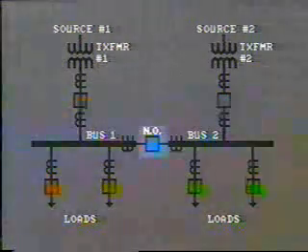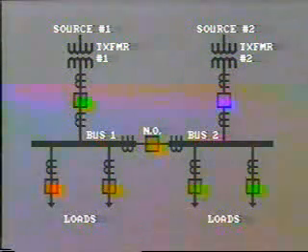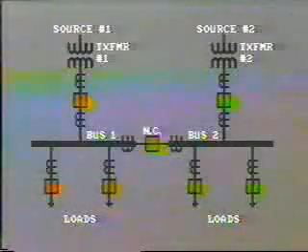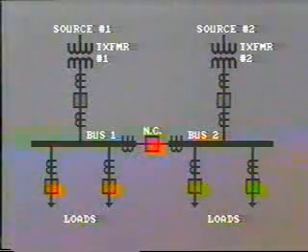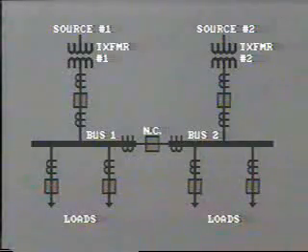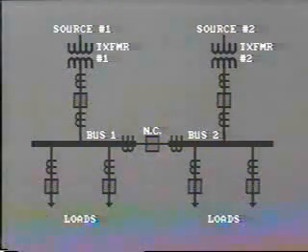The bus tie breaker will then be closed so that all of the bus can be fed from the single transformer, assuming, of course, that it has sufficient capacity. In some installations where uninterruptible power is required, the bus tie breaker remains normally closed so that both transformers feed all of the load. However, depending upon the configuration of the power system, this setup does have the potential for providing a path for backfeeding one of the sources.